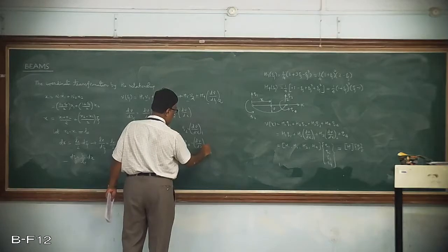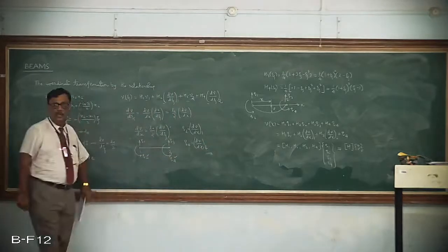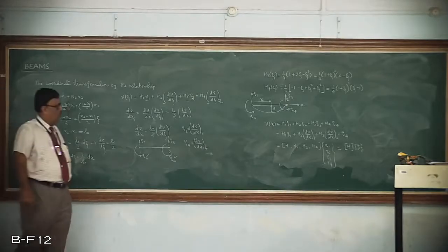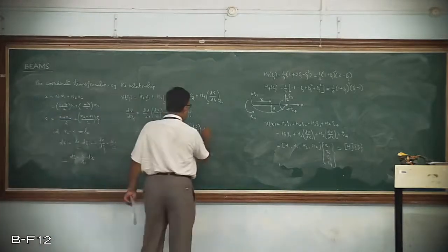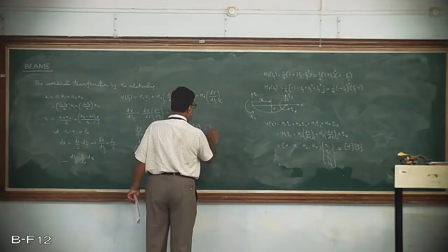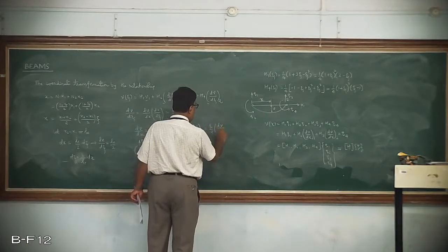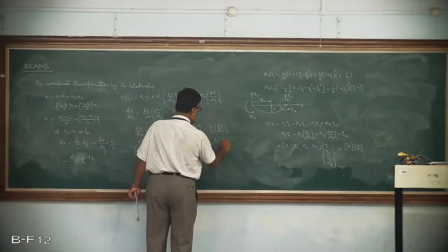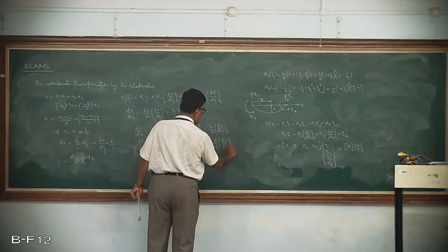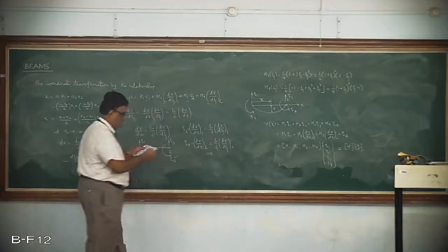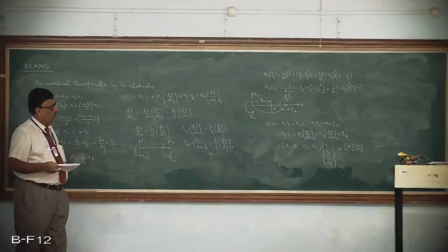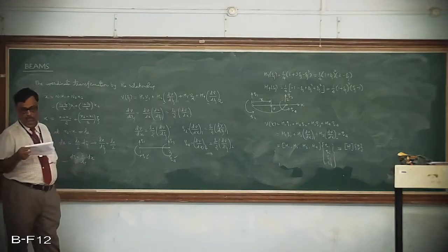This is with respect to the x coordinate. Always remember, slope is always defined with respect to the x coordinate. So, dV by d zeta at 1 equals LE by 2 dV by dx at 1, and similarly at node 2. This is the relation between Q2 and Q4.